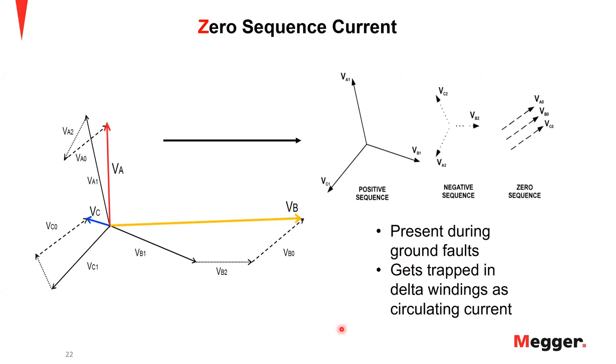So the next challenge is the zero sequence currents. Zero sequence currents are present in the power system when we have unbalanced faults. Like here is an example of an unbalanced fault, and any unbalanced fault can be resolved into 3 balanced vectors: positive sequence, negative, and zero sequence components. Now, using the symmetrical components, it's always helpful to analyze unbalanced faults. Today, I will not be talking too much about the symmetrical components. Rather, I'll be only focusing on the zero sequence current.